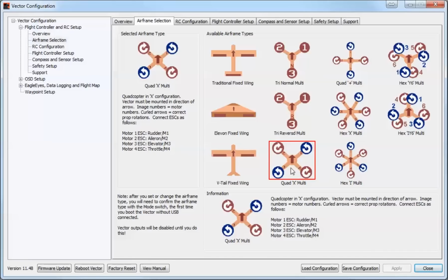One thing that you can do is a motor test. You can do that from the sticks menu. I've actually had a couple of problems with the motor test, which I'm talking to Eagletree about at the moment. However, the idea is that you can basically pulse the motor, which gives you the direction that it's going round, and obviously to make sure that M1 is M1 and M2 is M2 and not flip the wrong way round. So just bear that in mind. As always, if you get this wrong for whatever reason, if you find that something's rotating clockwise when it should be counterclockwise, brushless motors have 3 wires, all you've got to do is swap 2 of them over, boom, it'll go the right direction. So that's one for the people who haven't ever set one up before.